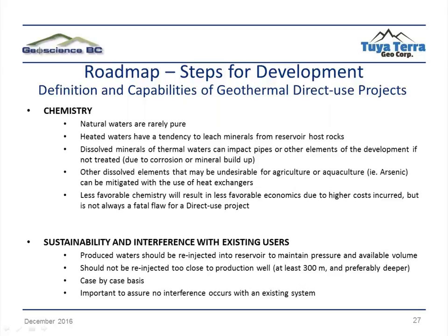So it has a lot of dissolved minerals in it that is not normal. What these dissolved minerals can do is cause corrosion. If our water chemistry is quite acidic, think like very strong vinegar, that acid can corrode our pumps and pipes and create big problems.